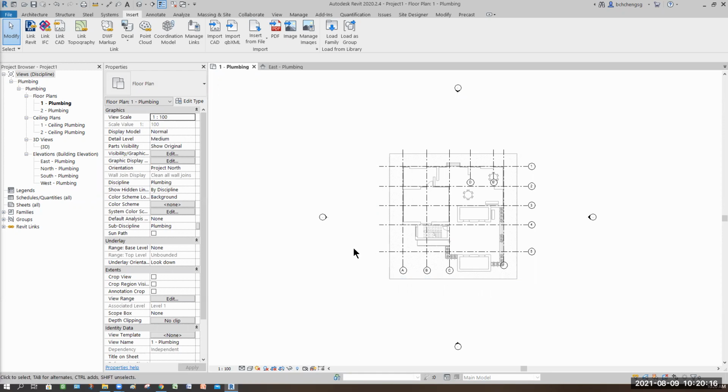Copy. Go to elevation, right? Grid also can, but if you don't want first, it's okay. Actually, the next step you should do is to link your CAD file. Why? Remember just now I showed you first story. What is the level there? Here totally don't have, right? So you got to do what? Link CAD file. Yeah, correct.